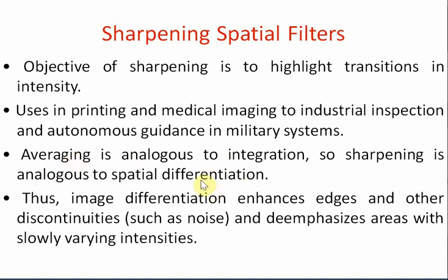Remember this point. Thus image differentiation enhances edges and other discontinuities and de-emphasizes areas with slowly varying intensities. It's a very important point. Image differentiation enhances the edges. That means we are using the high pass filtering action, which highlights the edges, so we can clearly observe the edges here, and other discontinuities also.